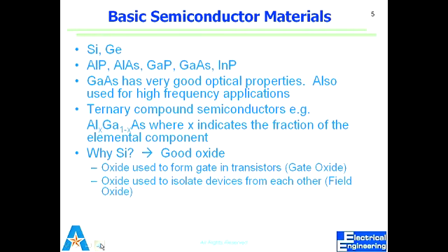So we'll get into that also, where we can change the band gap. Band gap is something where we have a valence band and a conduction band. Again, basic chemistry. For conductivity, for charge transport, we have to have an electron jump to the conduction band. So we can change that by changing the fraction. So you'll see ternary compounds most of the time written with subscripts. That will tell you maybe aluminum 0.3, gallium 0.7, and arsenic. So that changes the electrical properties of that material.